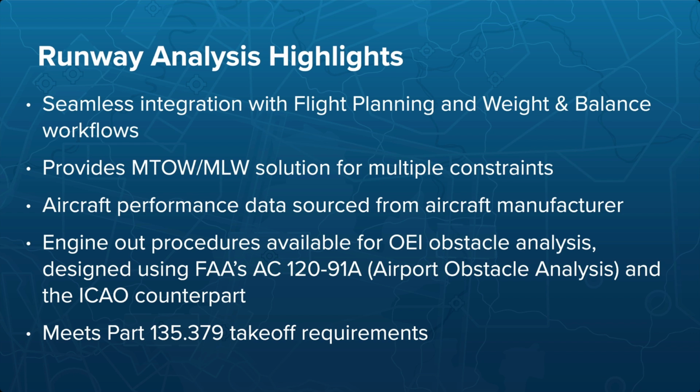We've also got some savvy tools that are automatically pulling forecast and actual weather conditions based on the time of departure and time of arrival, and automatically running calculations for multiple runways, resulting in our ability to automatically suggest the best possible maximum takeoff weight and landing weight, runway and engine out procedure where applicable. It's easy to change weather and runway conditions and aircraft configuration to recompute takeoff or landing performance before departure at top of descent. We also have Runway Analysis tightly integrated into our dispatch product, where again we're able to make those suggestions as a part of the flight planning process.